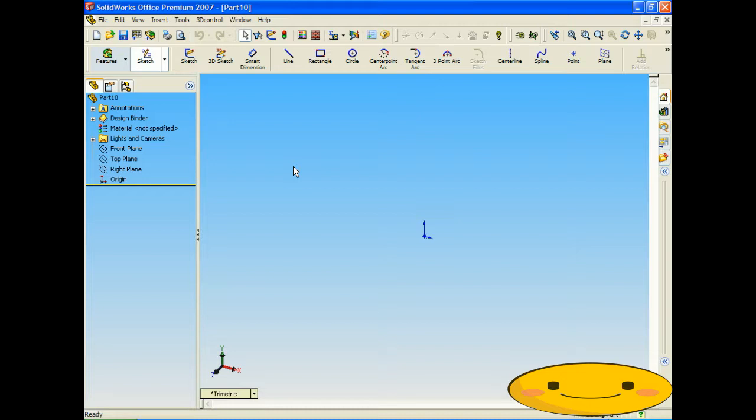Now, in the last tutorial, I talked about the intro to the tire and rim assemblies that we're going to be making. So, our tire and rim assemblies are 3 pieces. We're going to have 3 components that we're going to make: the rim, the tire, and the dish. So in this tutorial, we're going to make the rim. We're going to make an outline profile of the rim, and then we're going to be using the Revolve Base feature to make the rim and bring it to life in a 3D part.